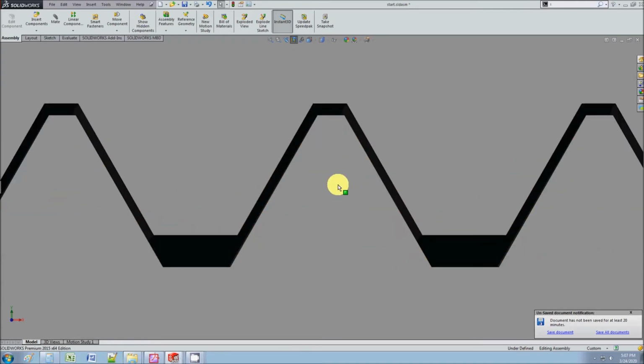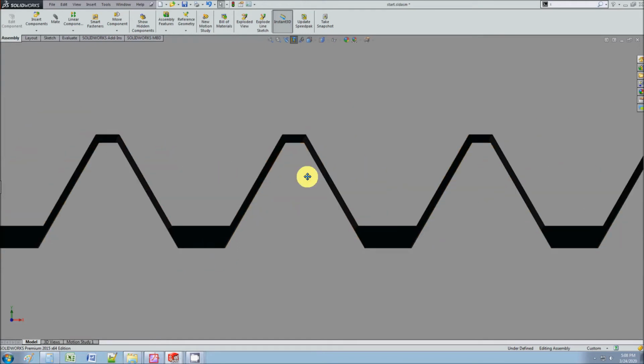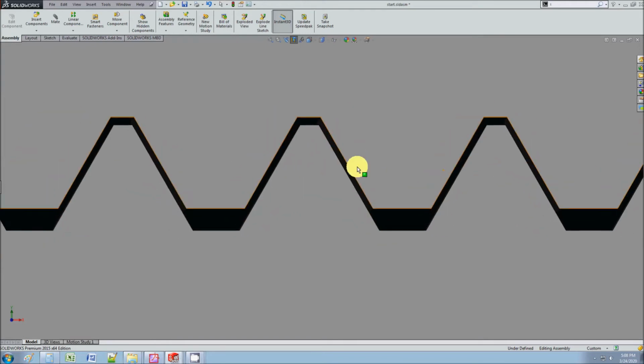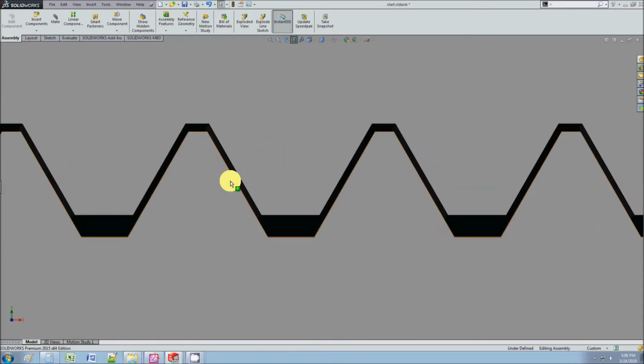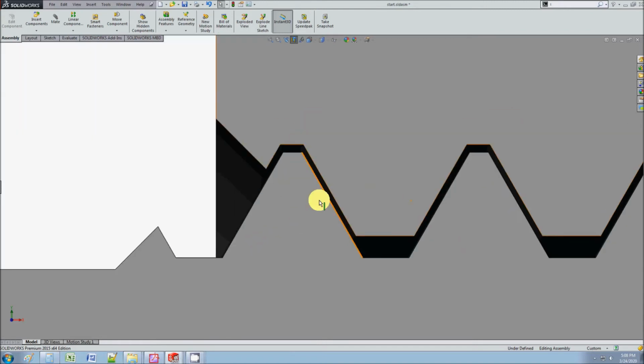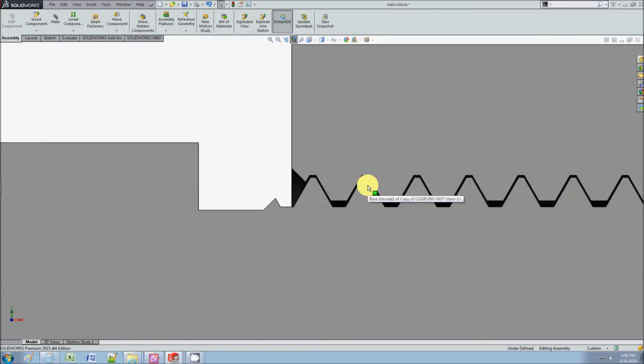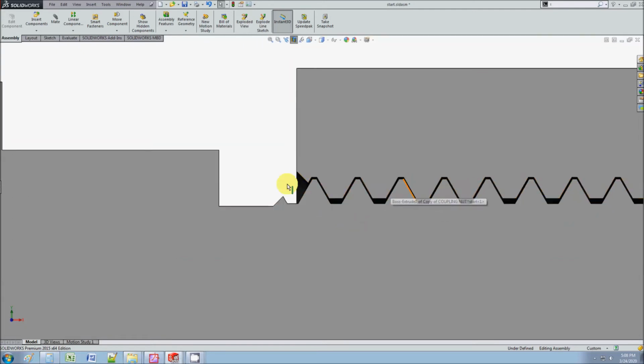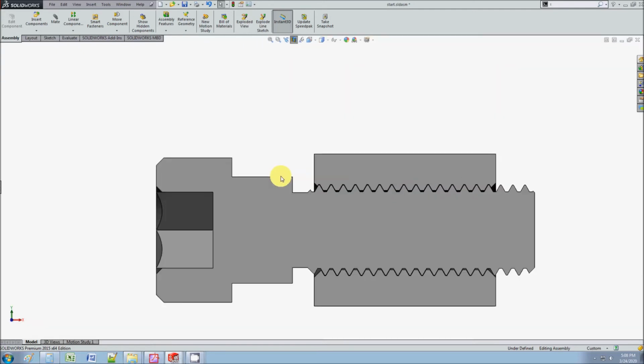For the project, I even encourage you to add a little bit more of a gap, just so that it clears really well. Okay, because FDM 3D printing is not very precise, so you may want to add a little bit more of a gap. But these are the nominal numbers for a 3/4-10. Okay, so that's a good thread. The numbers are right. Okay, so this is good.